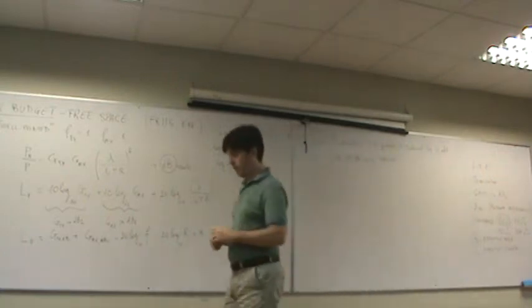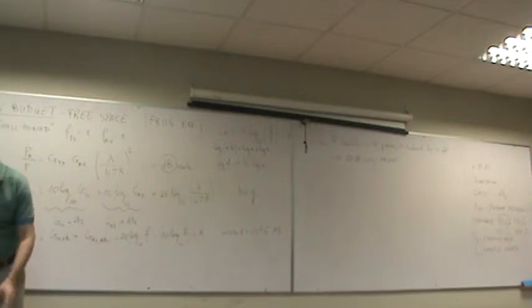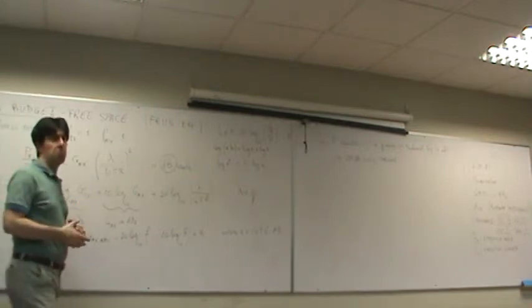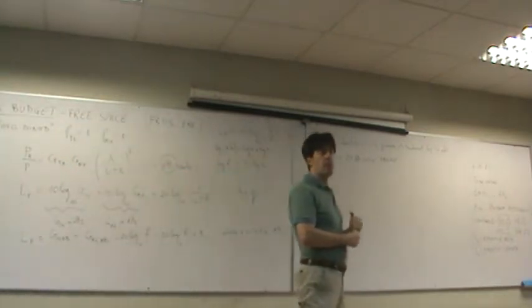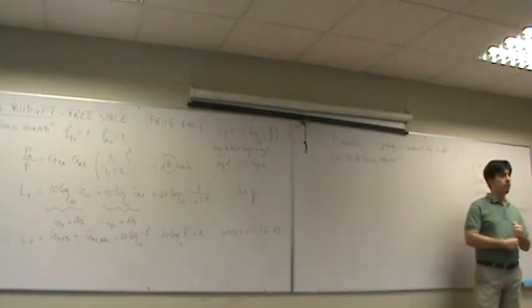This kind of information is useful when you have to dimension a link and you say, okay, if my distance increases by a factor of 2, you know in your head that you lose in free space 6 dB. So you can easily work out the link budget in terms of dB. Okay, and there is not much more to say about free space because nothing happens in free space. We will see that in the real world things will be very different.